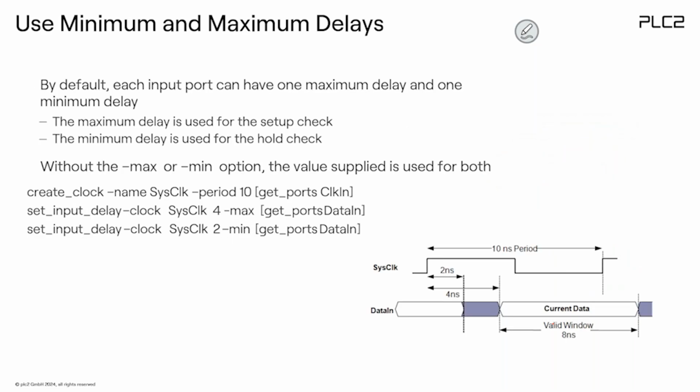So this means, again, this is the key for the input. First, you do have the FPGA here, and an upstream component here, and they have a clock. Could be the same clock, I don't care. Could be another clock, and then it's connected somehow here. But you have to define exactly this value. If there's a rising edge, for example, or falling edge, both is possible. If there's a clock edge here, then what's the behavior of the signal? So what is the minimum value and the maximum value?